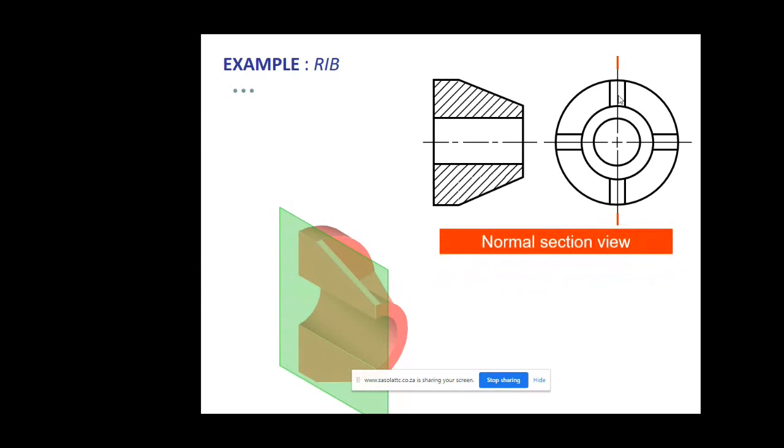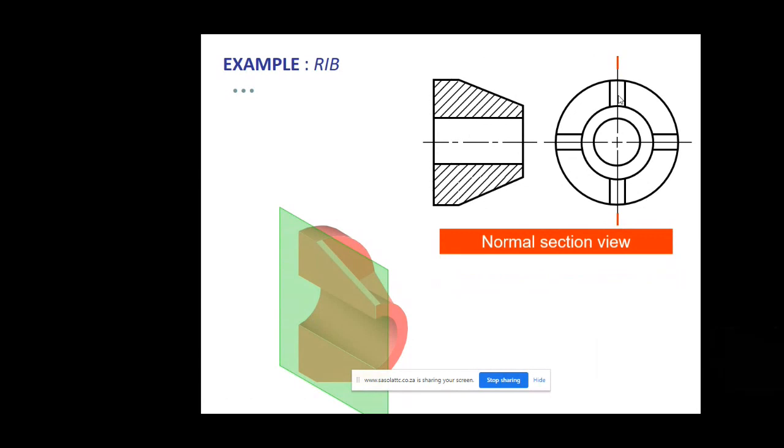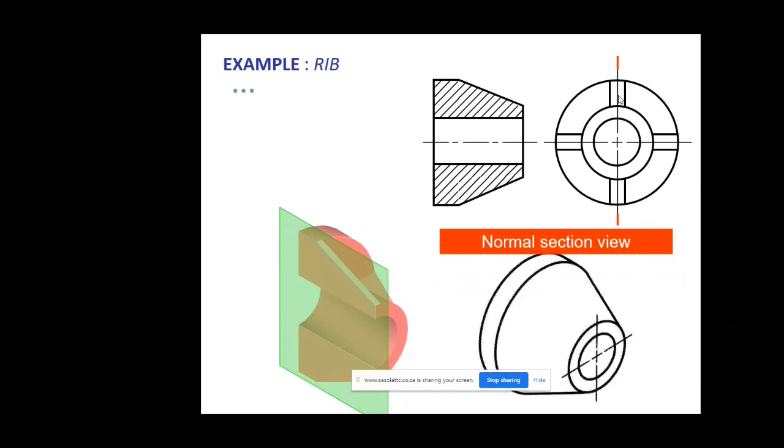And that will simply mean that they have a misinterpretation or a misconception of how the pictorial view looks, because now they have sectioned even everything. And we know that in EGD, much as we can cut a rib or any support, we should not show it in section, but practically we can cut it only to find the best solution. So a section like the way it shows on the front view would simply mean the entire pictorial view was drawn.